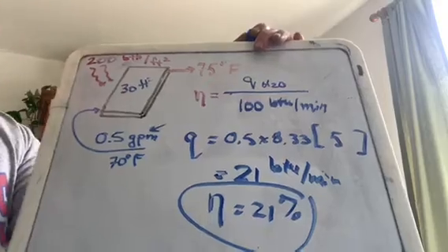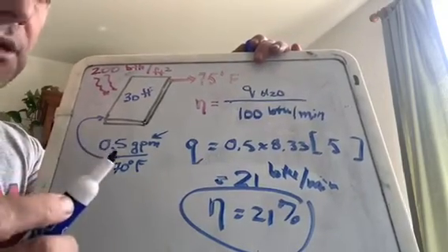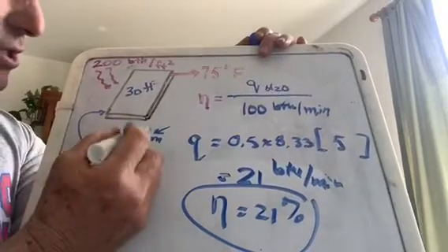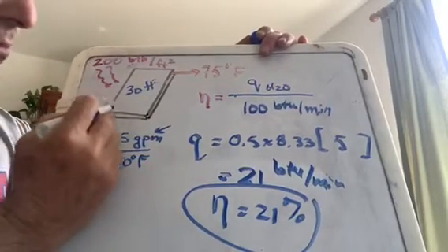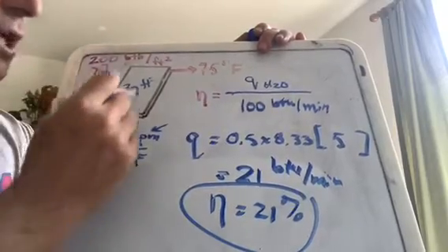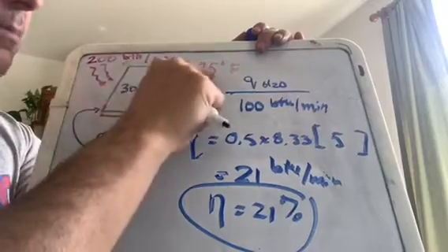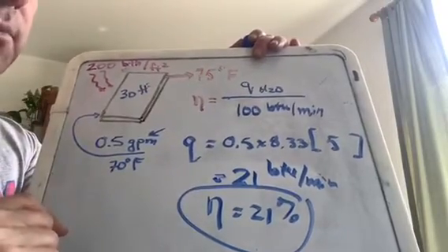So what we're going to do is try to change it to 1 GPM and see how it turns out. Here is a possible intuition. If I change this to 1 GPM, the water's going to be going through there faster, okay? And therefore it's going to have less time inside the collector, less time to warm up, and probably come out at a cooler temperature.